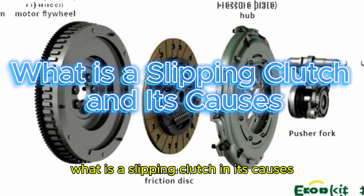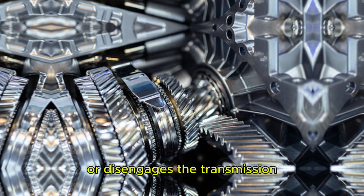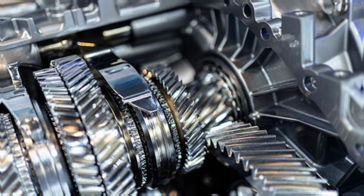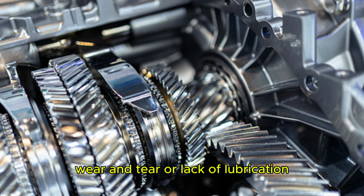What is a slipping clutch and its causes? When a clutch improperly engages or disengages the transmission, the car may slip out of gear or struggle to stay in gear when accelerating, known as clutch slipping. This can be caused by poor adjustment, wear and tear, or lack of lubrication.